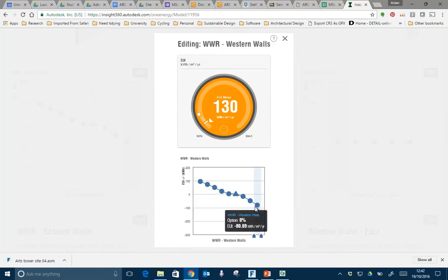If we went from that all the way up to 95%, then we've not only lost our minus 80 reduction, but we've added 95. So if we do that again, we're at 267 kilowatt hours per square metre per year for 95% fully glazed. If we slide that all the way down to 0 glazed, we drop down to 130. So immediately you see the kind of impact that these decisions will have.